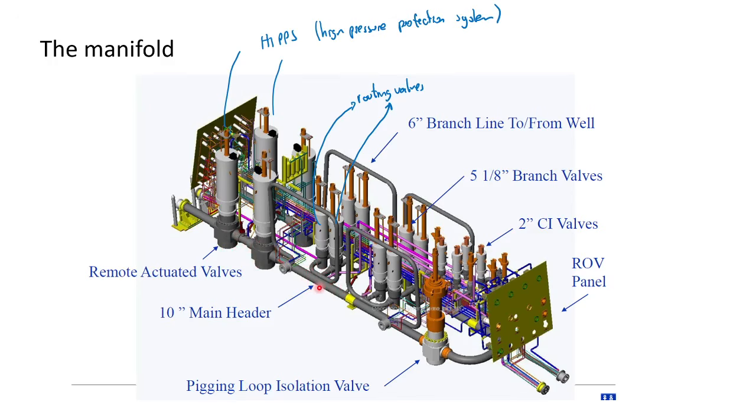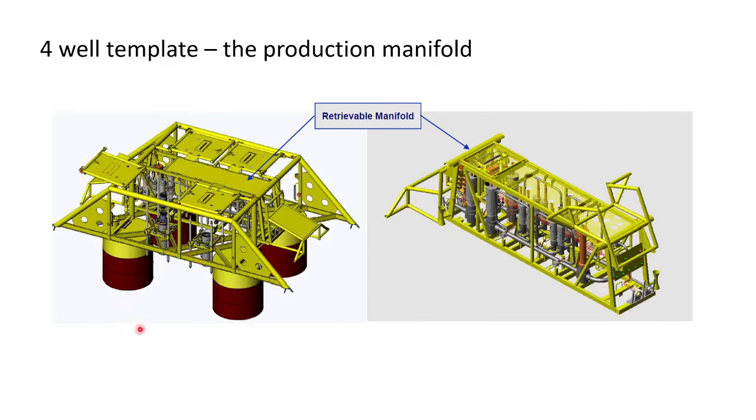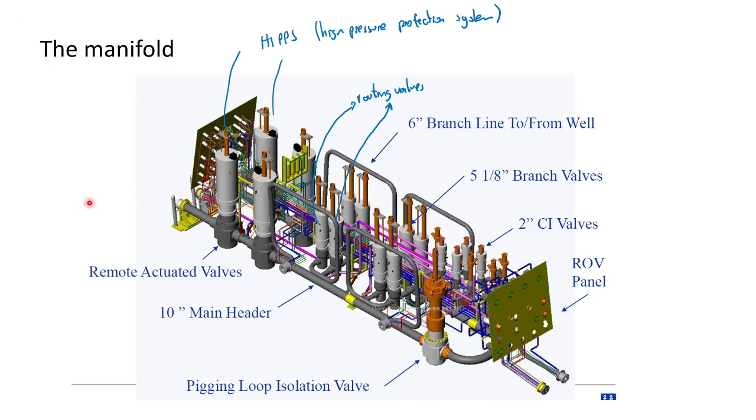However, the system downstream, which is the system on the subsea, so the whole subsea system, is typically rated for a lower pressure because then I can make the wall thickness thinner. I can save a lot of material. I don't have to make things that robust and big. If they are big, they are more costly and difficult to transport and install.